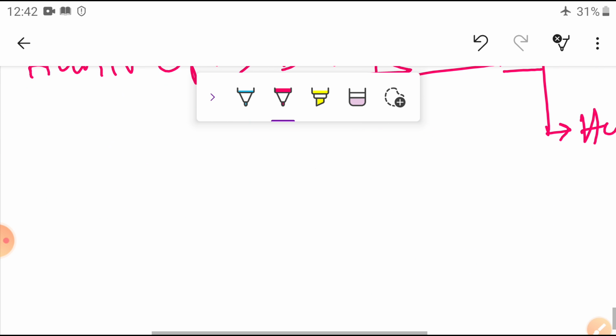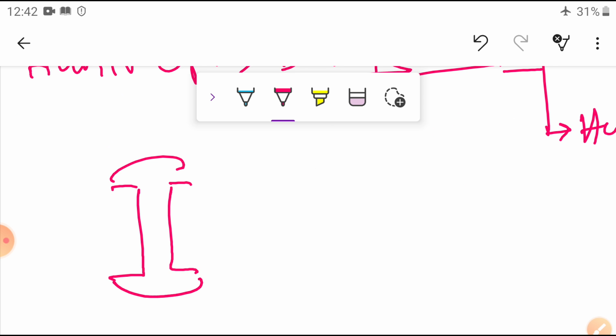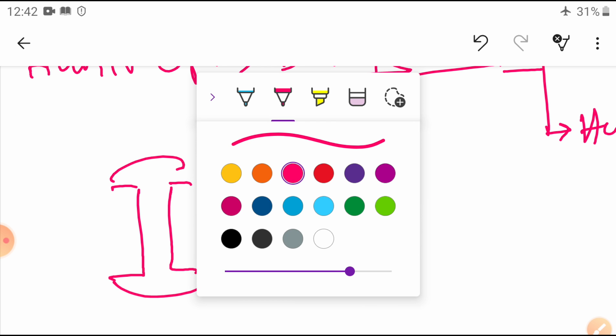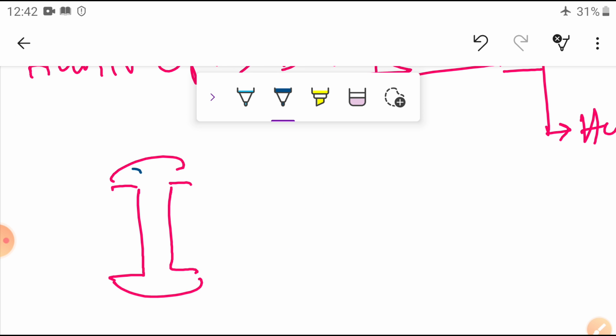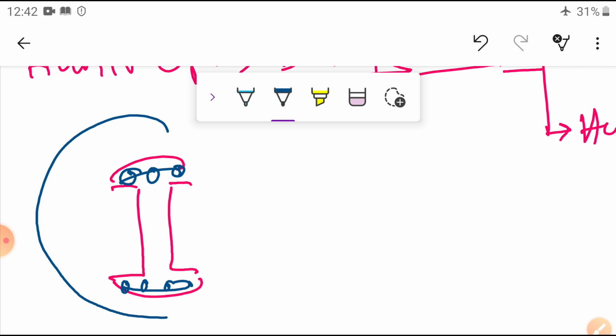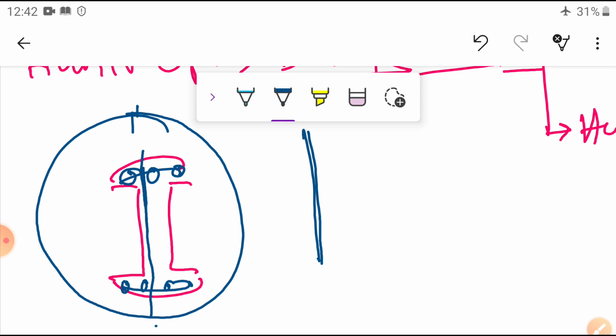So how are the damper windings used? Whatever the rotor poles have, damper bars are shorted at both ends. Under normal speed, the relative speed between the rotor and the synchronous rotating magnetic field is 0. Both axes coincide with each other, so alpha is equal to 0.